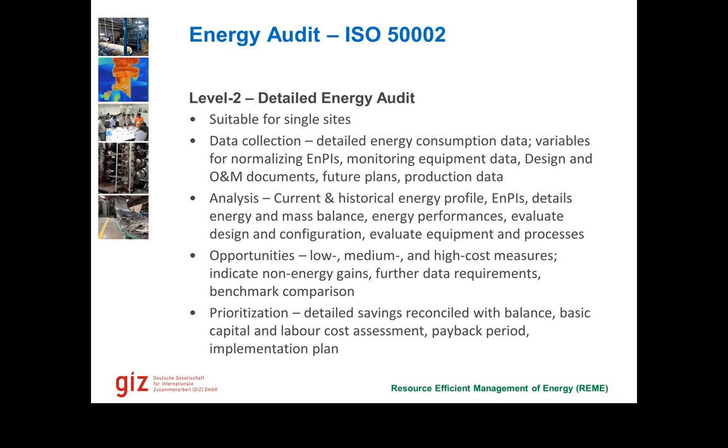It is important to understand that energy saving measures also have non-energy gains or non-energy benefits. For example, if we improve parameters of a garment washing process in a way that it requires less energy, for example, we have a hot wash, and with a change in chemicals, we convert it into a cold wash. That would mean that we don't need any time or even less time now to heat up the water in the machine. So because we need less time to heat up the water, our batch time reduces by 5 minutes or 6 minutes or 10 minutes even sometimes.